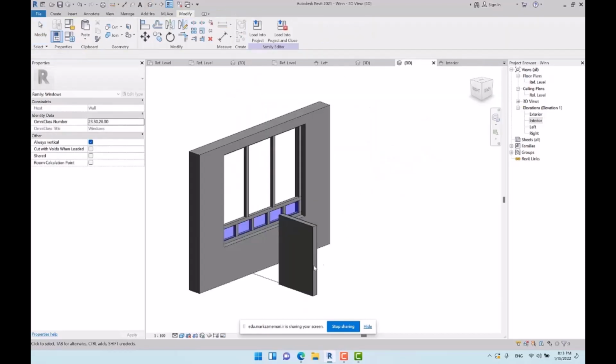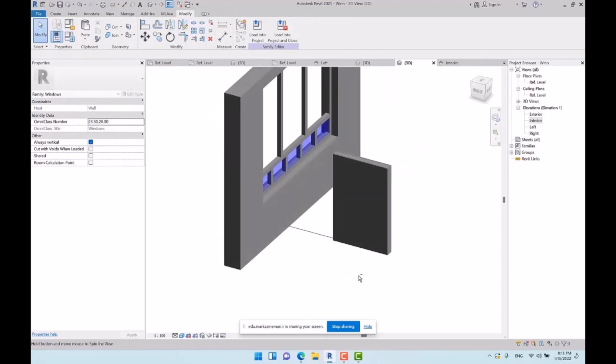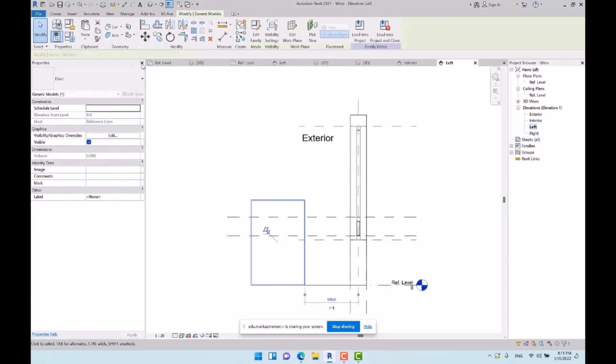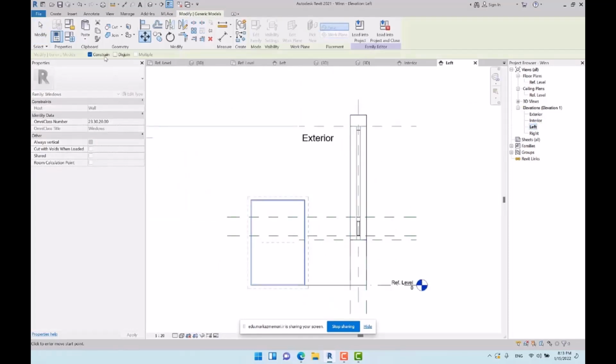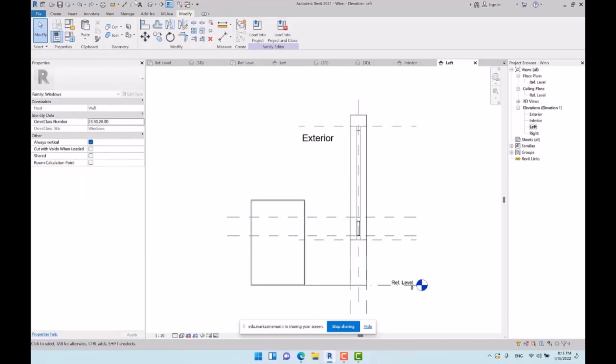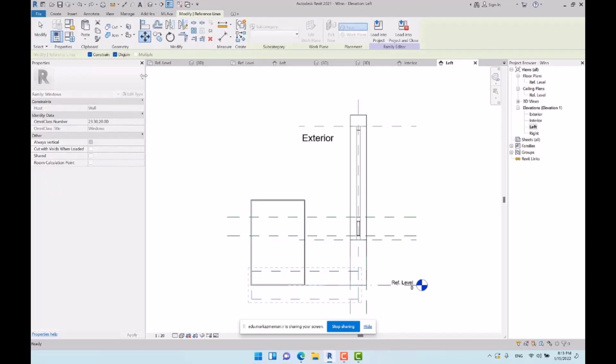After that, the way we should move the reference line, at first we should select it, but do not take it as a mistake since you're not able to move the panel. Even if I uncheck constraint, as you can see, the panel is not allowed to be moved, and if I click on this join, it is no more connected to the reference line. So what is the best approach? Is to select the reference line.